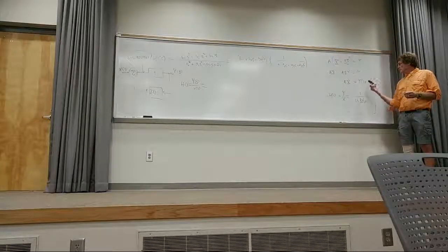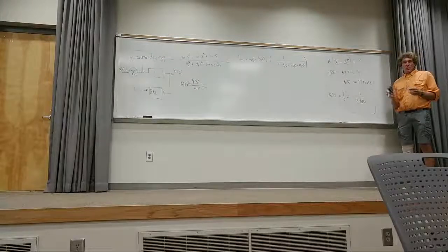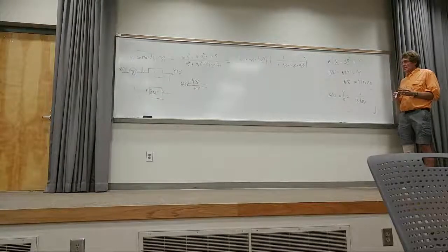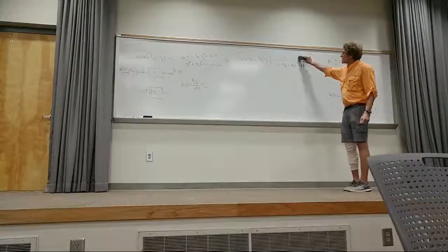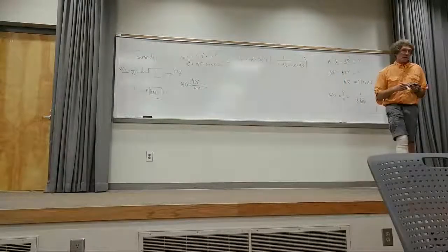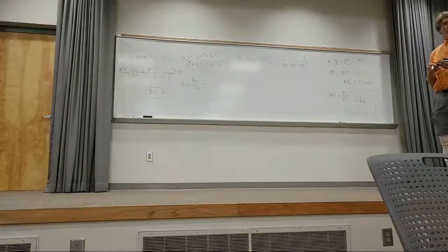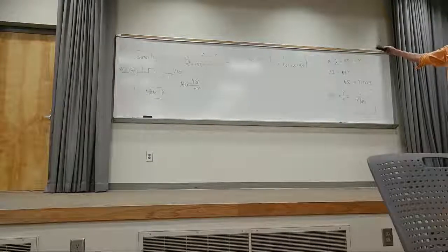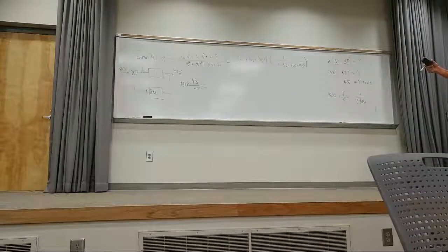The only thing I did was make the forward gain A equal to 1. So anywhere there was an A, I put 1. Are you with me? Can you explain why you did that? Yeah, because now it fits the form right here perfectly. You follow that? I have 1 over 1 plus whatever that is, A1 over s plus A2 over s squared plus A3 over s cubed, that's B of s. Do you all follow me on this, guys? It fits perfectly, doesn't it?